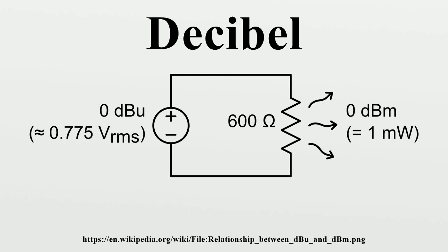In electrical circuits, dissipated power is typically proportional to the square of voltage or current when the impedance is held constant. Taking voltage as an example, this leads to the equation, where V is the voltage being measured, V0 is a specified reference voltage, and GdB is the power gain expressed in decibels. A similar formula holds for current.